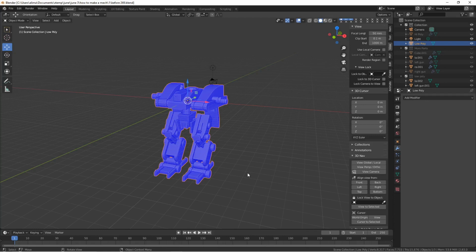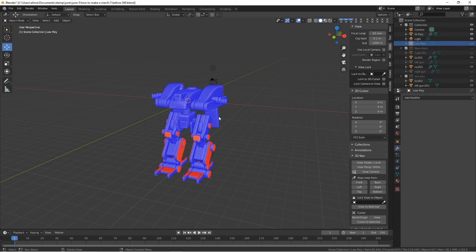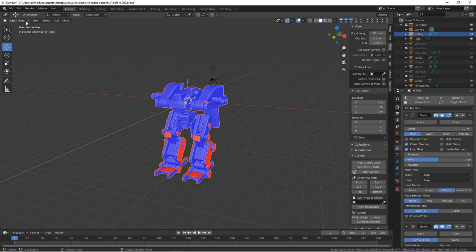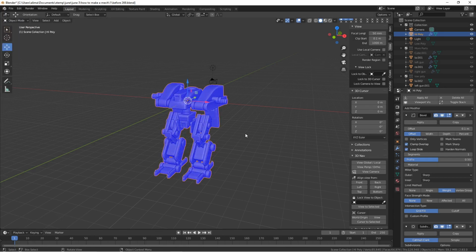Okay, so we can keep this face orientation on. We can go to our objects. We'll quickly be able to see what is correct as far as our normals. So we're going to hide the low poly, bring in the high poly. We can see this has issues, so we'll select this. We'll go to the upper left. We'll go to edit mode. Press A, hold shift, press N. So now that's correct. I'll left click to deselect. Go to the upper left, go back to object mode.